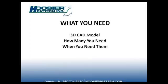So get your number of castings you think you're going to need at the start. Coming back later can be an issue on timing. The other thing is casting simulation or solidification. It should be run. Again, this can be run by you, by us, or a third party. It is important to perform this calculation to enhance your chances of successful outcome. We don't want to cast and pray over a casting and hope we get it. We want to be guaranteed that we get a good casting every time we pour into a 3D printed mold.